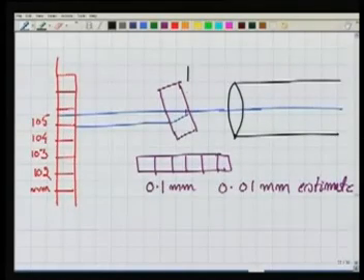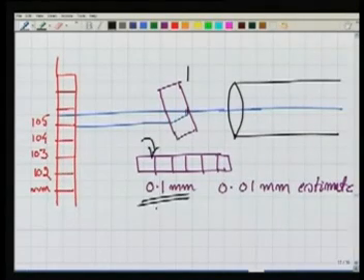It has been rotated by something, and the corresponding value, how much we really rotated it, we take here. Using this, we can measure up to 0.1 millimeter, and then we can further estimate up to 0.01 millimeter. It depends upon the different micrometers or these different precision leveling instruments, what kind of instrument it is, and what final precision it will give you.